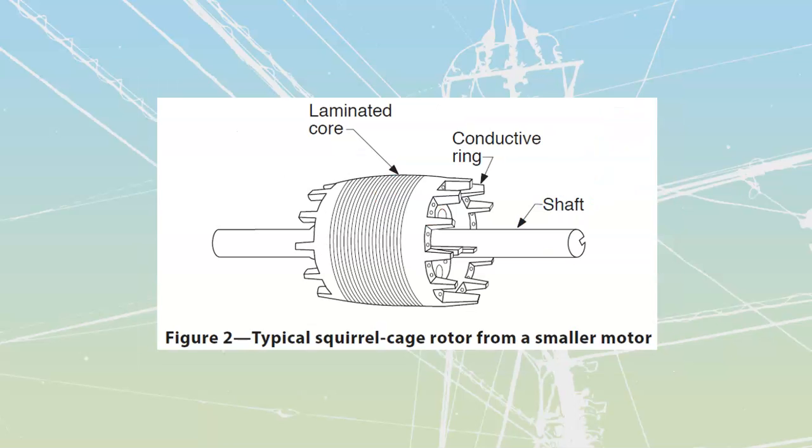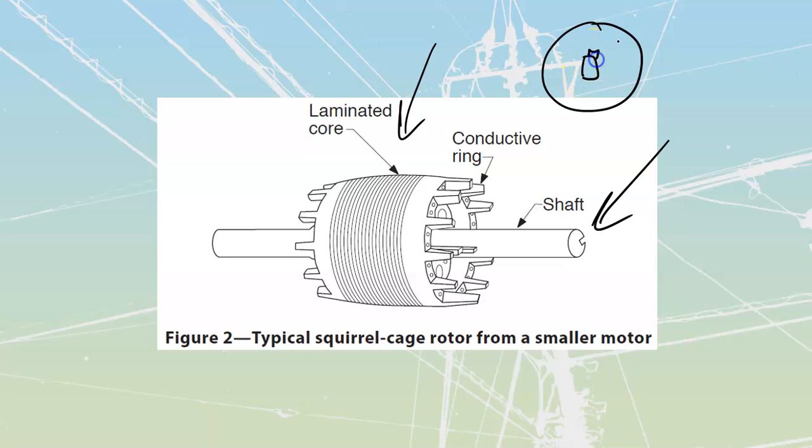The next component we're going to talk about is the rotor. And the rotor is an actual winding. It is going to be a cylindrical laminated core. So over here, they're going to take a shaft. They're going to mill out a bunch of these laminations. They're just going to be circular components that have a keyway inside of them for the shaft, etc. And then they're going to be epoxy dipped.